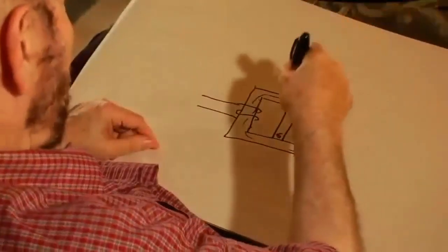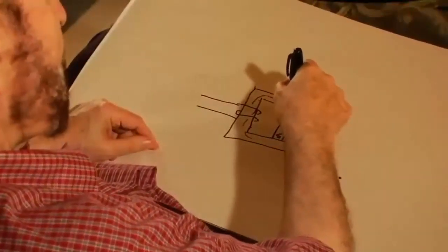And then I take an instrument with a field probe to measure magnetic field B, and I put it right on, let's say, that north pole. My instrument measures no magnetic field, or almost zero. It's impossible to get total contact. You will have the tiny, tiny air gap, so you will measure a tiny, tiny field. But essentially a zero magnetic field right on the surface of the magnet. Now that proves that all the magnetic field that normally spilled out of this magnet everywhere has got sucked into this core and is sitting there.